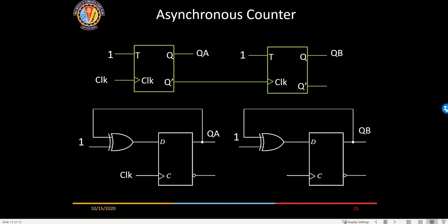Okay, understood. Correct. If you see a frequency divider making T flip-flop, which is there in the tutorial also, we have given JK, the output of the first JK as a clock to the next stage. And since they don't have the same clock, they will be termed as asynchronous.